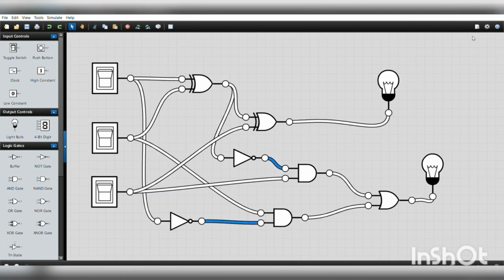We had earlier seen the design and implementation of a half subtractor. And now we are going to see the design and implementation of a full subtractor. A full subtractor generally consists of an XOR gate, NOT gate, AND gate and an OR gate. So the output is given by the difference and the borrow equation, where the difference equation is A exclusive-OR B exclusive-OR C and your borrow equation is C into (A exclusive-OR B) the whole dash plus A dash B.